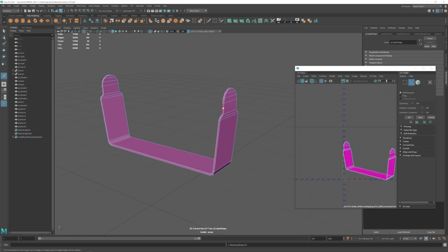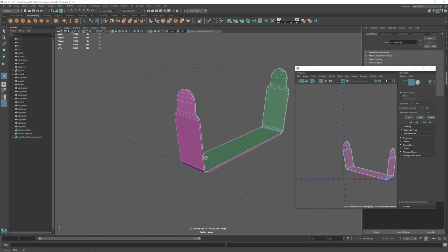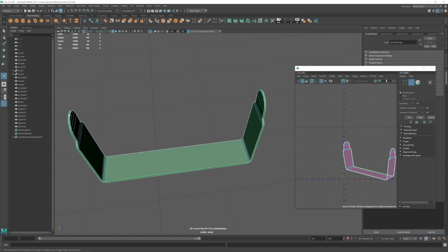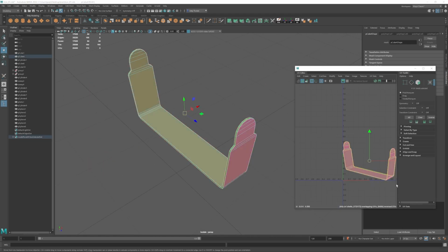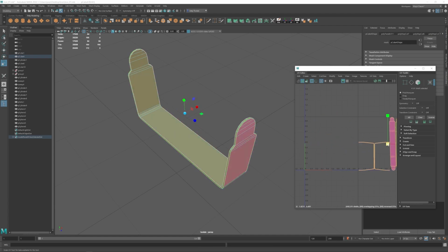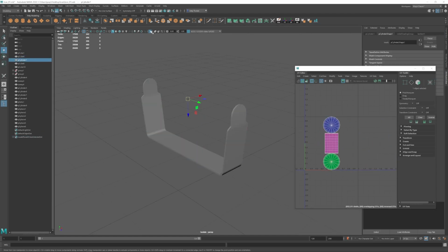Oh yeah, one quick thing about this shape specifically, I end up changing it later on because I end up doing 2 cuts around both of those edges, and you get those extra UV shells on your UV map, and they're a weird shape and it's just unnecessary. So what I end up doing is just removing one of those cuts. That way, it's basically just 2 UV shells and it looks much better.